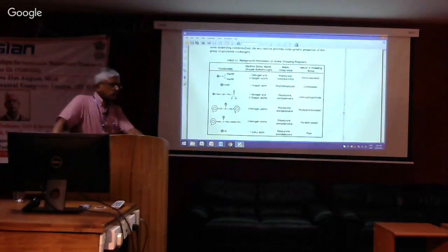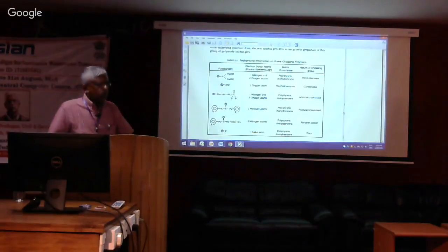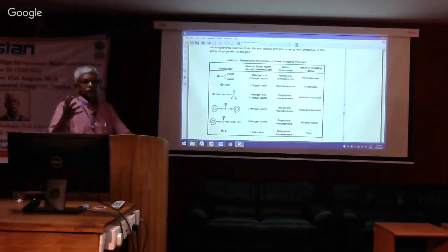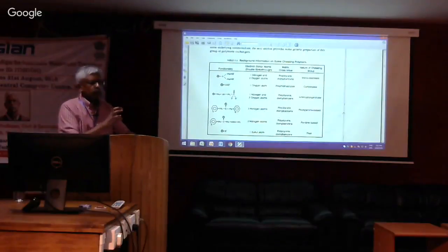Well, for hardness removal, most of the time we use a strong acid functional group because the typical concentration of calcium and magnesium in the water is such that it kind of helps us in the exhaustion process.